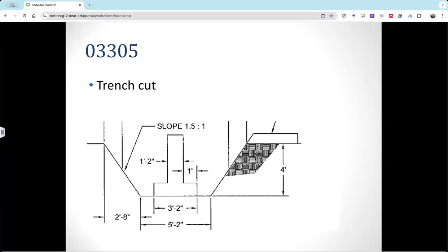So that is the change outs. You will see your strip footing is over here, but you are cutting this way. You are not only cutting your earthwork for exactly the same shape as the footing, right? You need more working space, so you are cutting in this way.